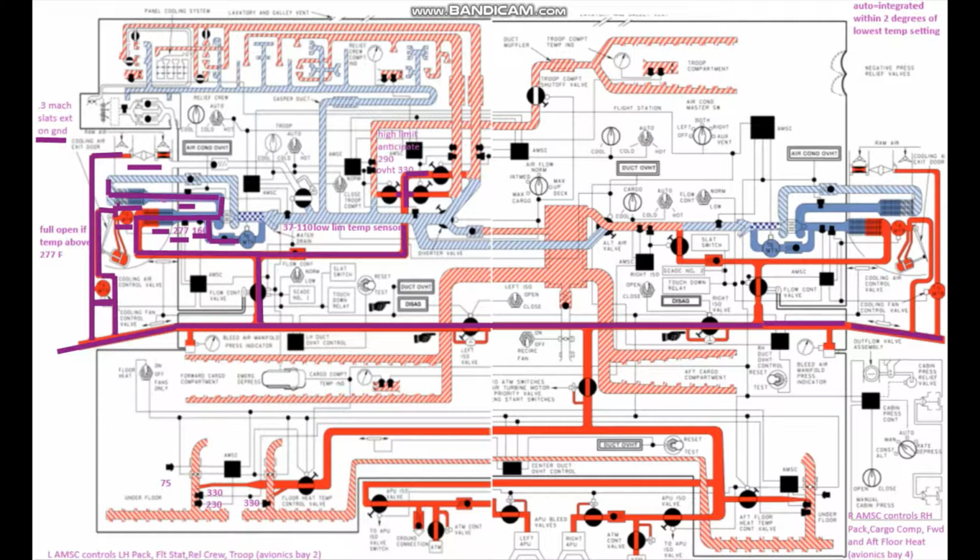It'll come up and around through ducting, overcome a check valve, and then it'll hit the rapid expansion portion of our air cycle machine. And what that does is, as it rapidly expands the air, it supercools the air and removes the moisture, so you end up with very moist air at this portion of the air cycle machine.